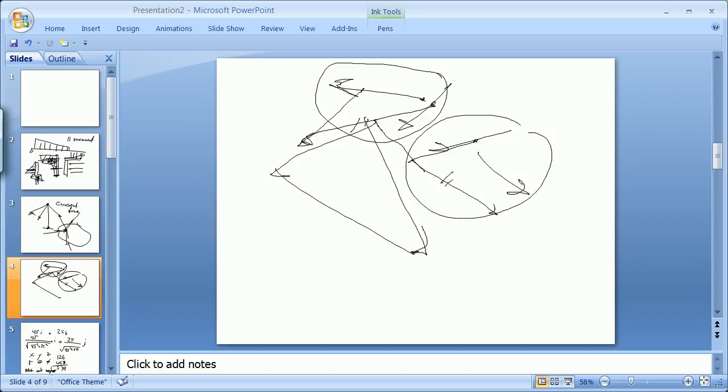to something like that. So that graphic use of non-parallel non-concurrent forces is something you should practice and be able to do pretty quickly so you can get a good result by sliding triangles, and we'll get some practice in that as we go through the semester.